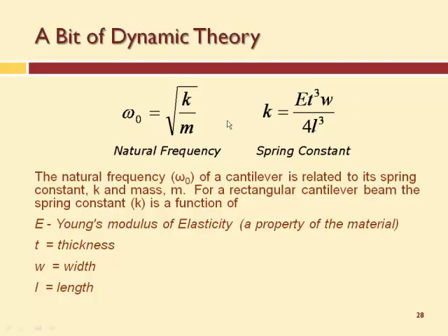So, in theory, could you accomplish the same thing, let's say, with a 2-micron thickness as with a 20-micron? Yeah, you can change the thickness and the width, or just the thickness, or just the length, or the thickness and the length. You can do any combination you want to get a specific K. And you might have 10 different ways to get the same K, or 100 different ways, right?